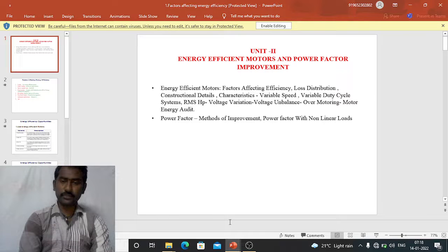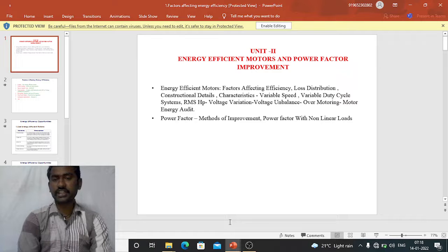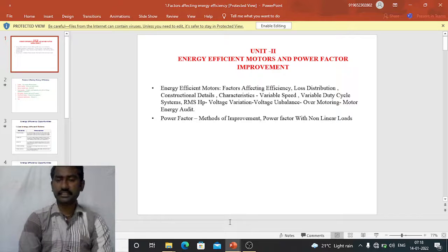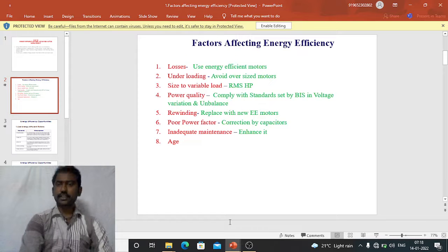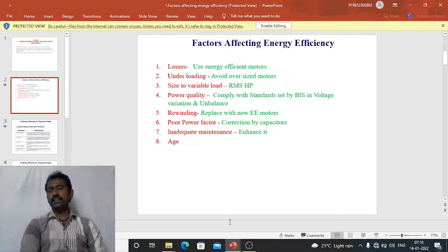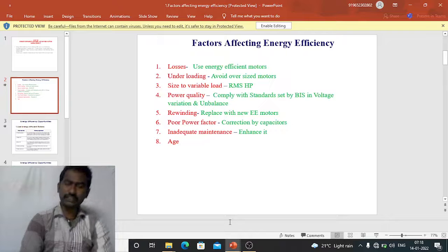So in this video, I want to discuss the factors affecting the energy efficiency, loss distribution and construction details with 3 PPTs. So let us move to our discussion. What are the factors affecting the energy efficiency? Here mainly 8 factors are there. What are the 8 factors? First one is losses. To reduce these losses, we use energy efficient motors. And what is the second factor? Underloading. To overcome this underloading, we can avoid oversized motors.